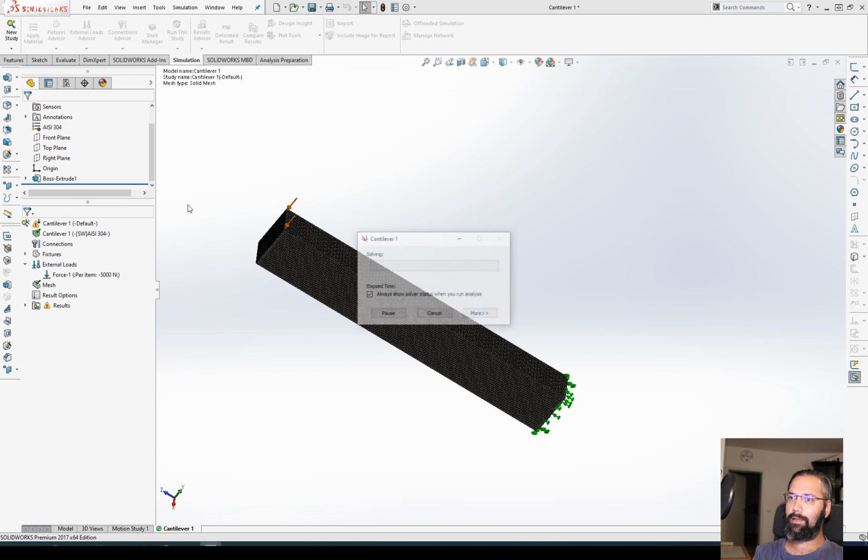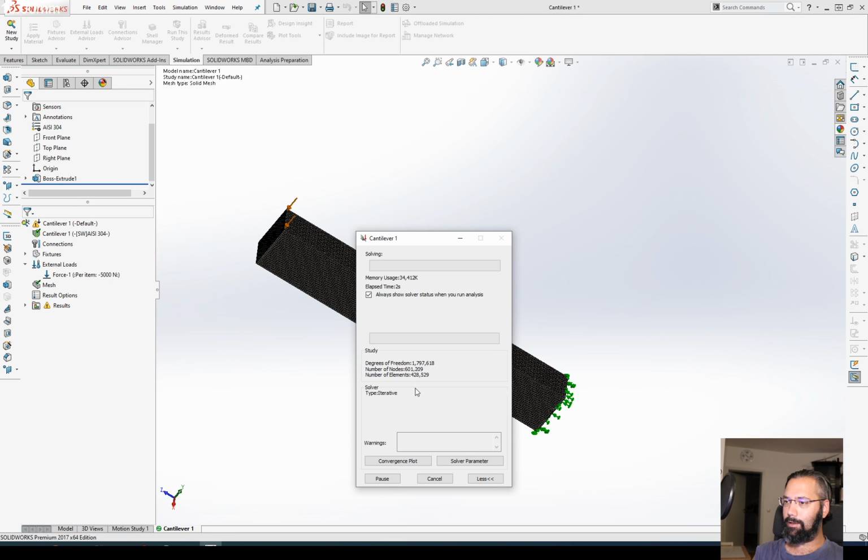It's fine. How many elements do we have? You have 500,000 elements for a simple beam. This is way too much. You should probably have like 1,000 elements here. It would maybe be interesting to see how low we can go on elements and still get the same result.